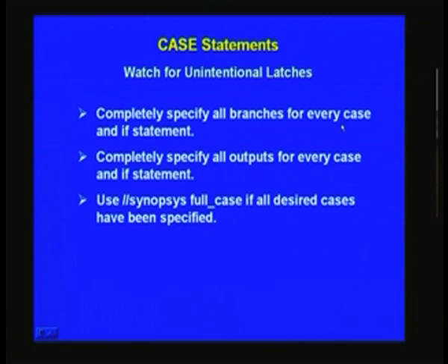At every case statement, for every possibility, you have to consider it wholly. So also for if else if statements, you have to consider all the possibilities. Do not leave anything to chance, otherwise you will get into trouble later on. The synthesis tool itself will not permit you to go beyond, and even if you wade through all the tools, finally when you make the chip you will see that it does not work when you hook up the circuit.